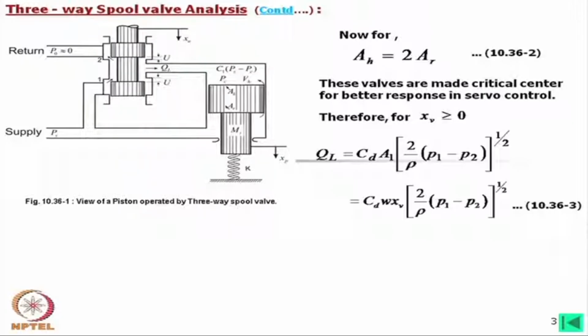Sometimes instead of this continuous groove, some rectangular holes are provided. If this is with rectangular holes, say 4, 5, 6 holes over the periphery, and they are usually equi-spaced, in that case also we can use this formula, where W is the width of each hole through the sleeve times the number of such holes.